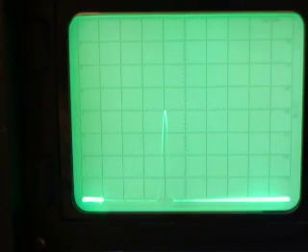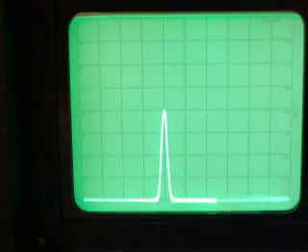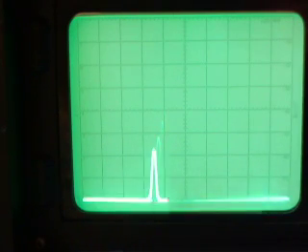So the scope that you can't see, but the scope has gone from showing a very clean sine wave to just showing a bit of noise. I'm sure if I altered the volts per division we could see something on the scope, but there's a lot of attenuation going on there already, and all I'm at now is 9.99687 megahertz. So if I continue to drop this down, you'll see it drops and drops and drops right until it's so far in the noise it's just not worth talking about.